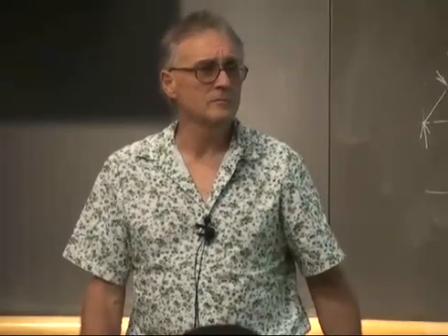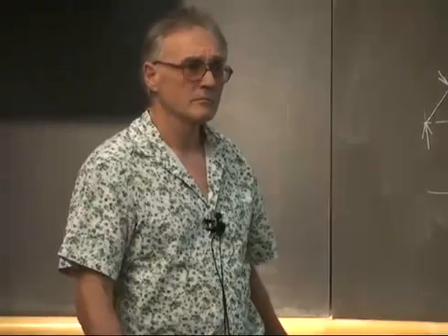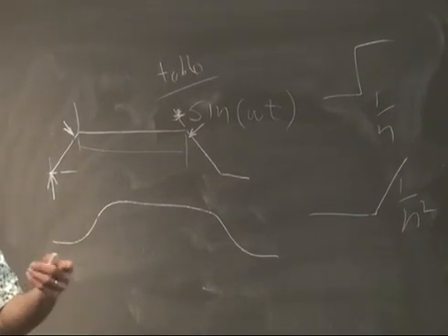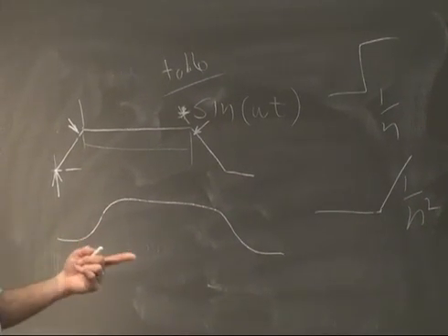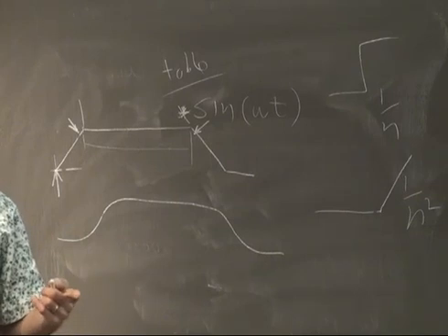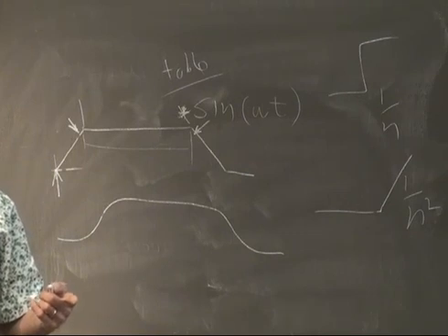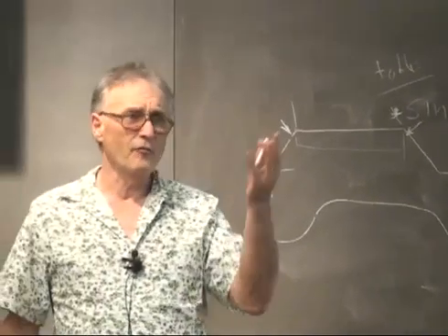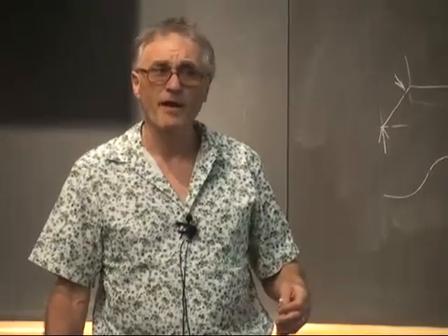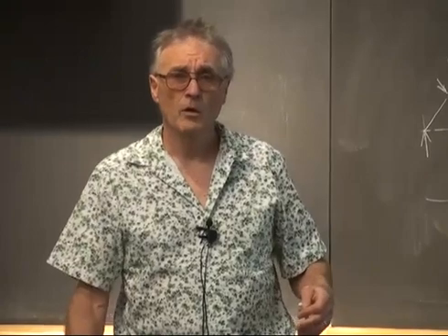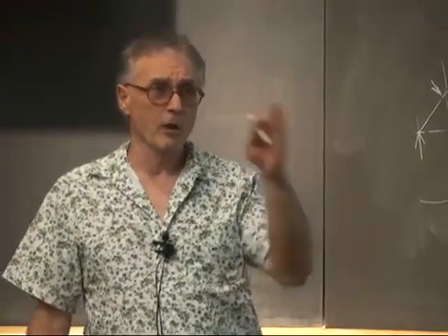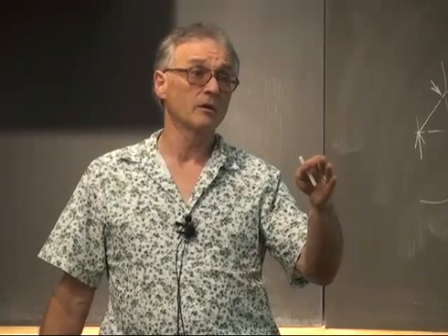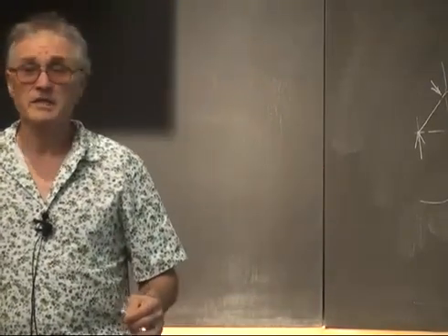So we have to modulate two signals together. Why not just use a multiply? Let me say that the multiply in this architecture is rather fast. For two 16-bit values, it'll do this multiply in 2 cycles. For a 32 by 32 multiply, it has to do 4 of those. It's still pretty fast. So unlike some microcontrollers, a multiply is not a problem on this architecture. And for that matter, divide is in hardware also, which is fairly unusual. It's a 17-cycle divide.